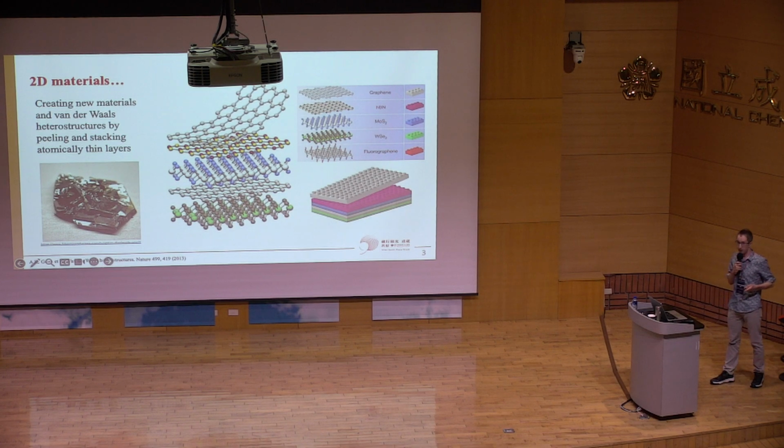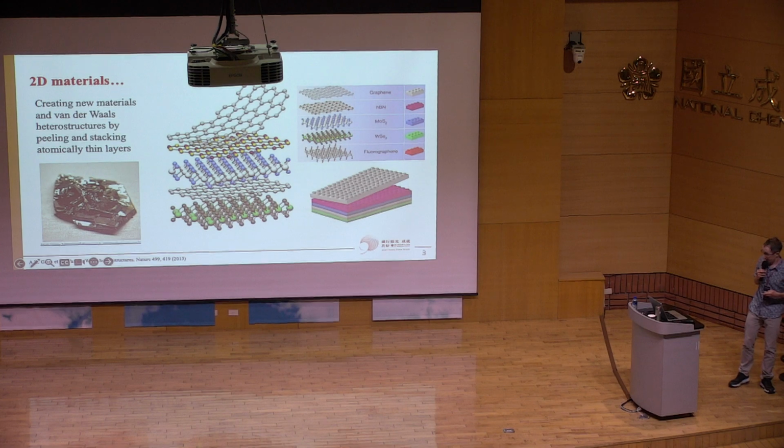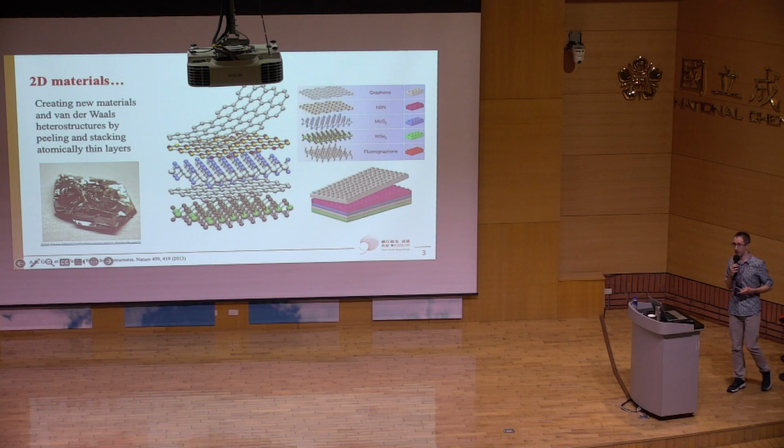In the lab, what we do is we take a piece of sticky tape and stick it onto the crystal. You can then peel that tape off, and you're left with some material on the surface of that sticky tape. You then stick that onto a host substrate. We use silicon wafers, which have a layer of silicon dioxide on top. Then you peel the tape off, which leaves you with some two-dimensional material on the surface of your substrate, which you can then look at under a microscope, find flakes of different size and thickness, find the one you want, and continue the rest of the fabrication process.